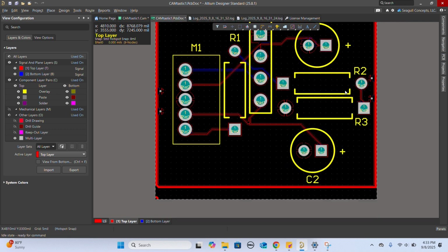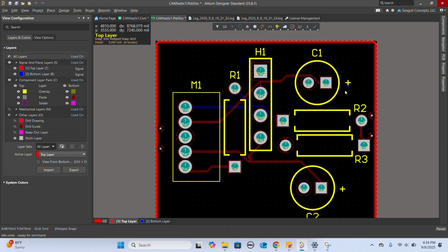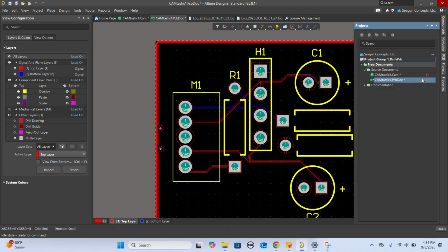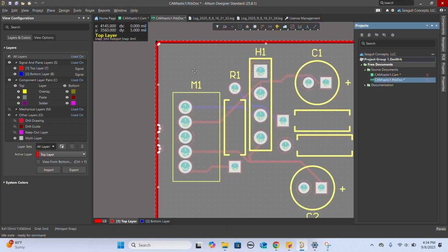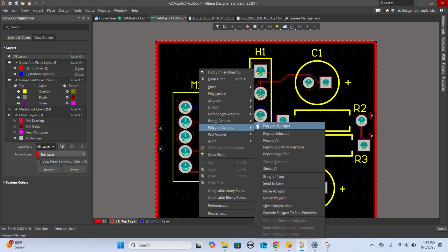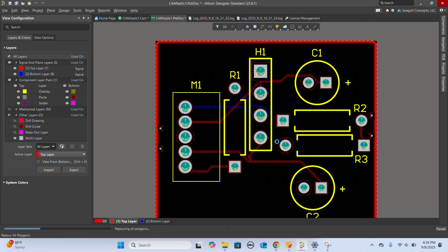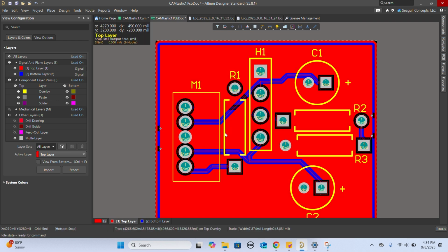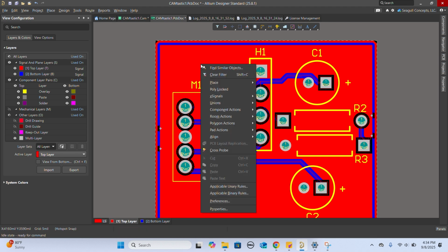The next overall step that we're taking here is to export to PCB, where we're going to try to get a PCBDoc file generated with 2 different layers. The reconstruction's not done, however. We're going to need to do some manual cleanup with polygons. There are empty polygon and copper pours, which we must fix manually.